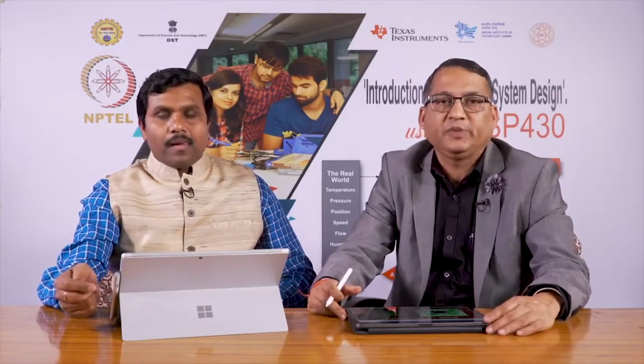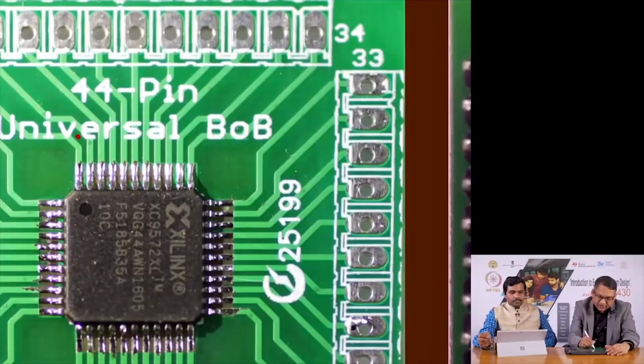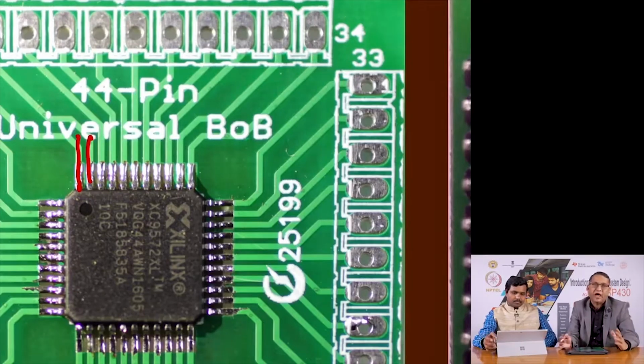Now, as I mentioned earlier, oftentimes you may need to use a surface mount device, and the issue with surface mount devices is the distance between the pins of an IC or a component. The distance has been reduced significantly, and the other problem is that there is no uniformity, no standard. A normal DIP IC has a distance between pins of 0.1 inch, but surface mount devices have a variety of pitch. In this case, the distance between these two wires is relatively large for an SMD, and there are other SMDs where the pitch of the pins is even narrower.